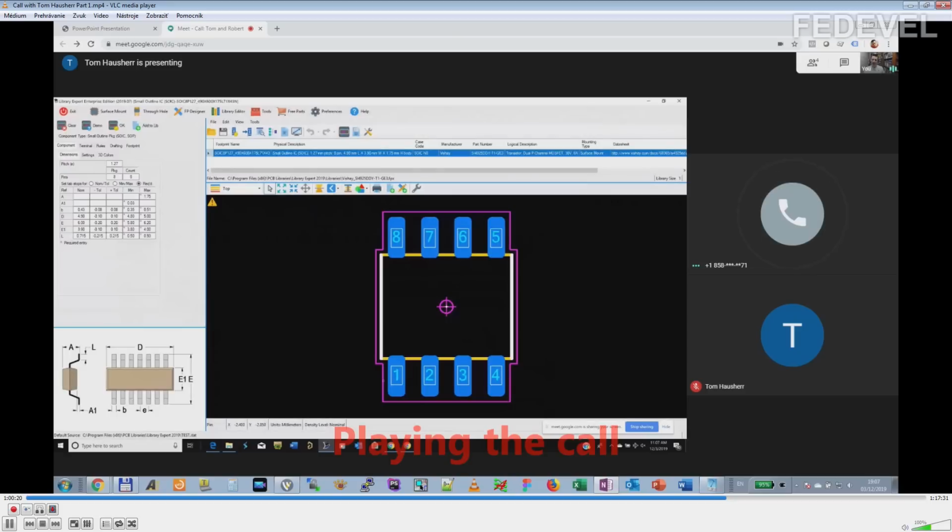We can't have it because the solder may spread and cause some short circuits. If you're using a fine pitch part, like a 0.4 millimeter part or whatever, you could have solder bridging. We have no reports of solder bridging yet. Nobody has ever reported this, because what happens is that when your plastic touches the solder, it pushes the solder into the heel, up the side of the lead. So there's no solder bridging going on, because you have solder mask in between the pads.